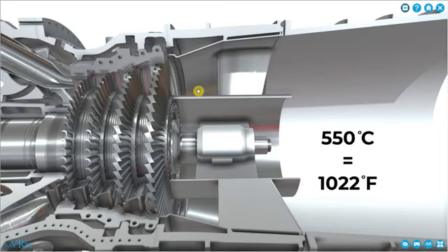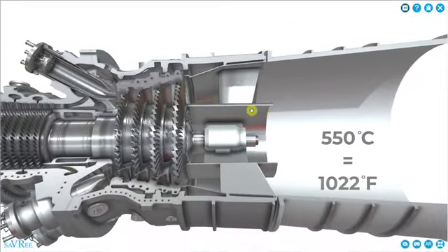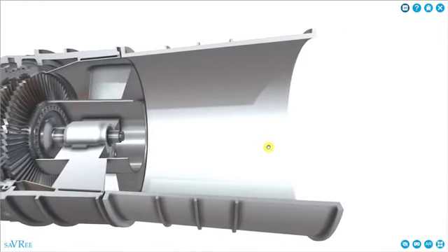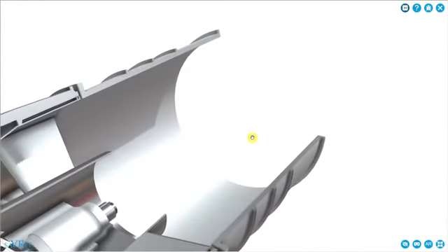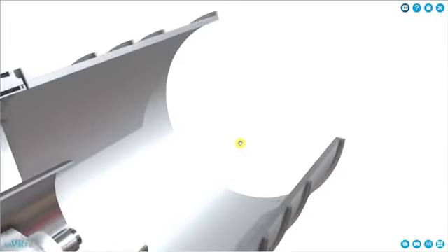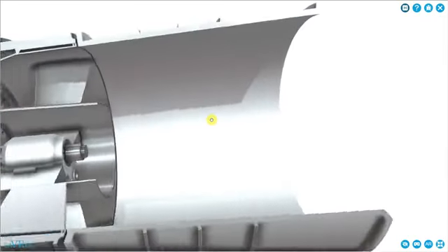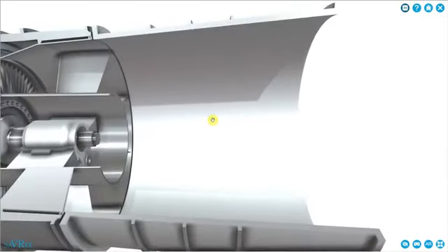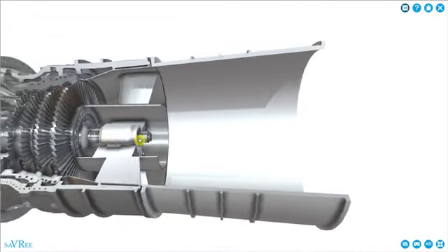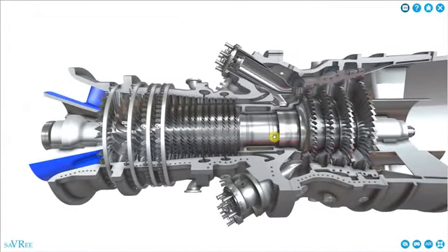When we discharge the hot air at this end here, it may be 500, maybe 550, 600 degrees Celsius in extreme cases, and that's quite a lot of energy that we're going to discharge just potentially straight to atmosphere out through this hole. So rather than do that, what we can do instead is connect the gas turbine to a steam system. This will increase the overall plant efficiency.